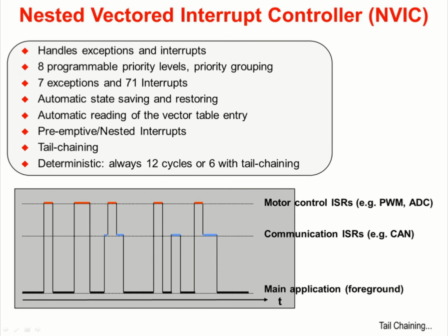One of the first rules that you learn when programming interrupts on a microcontroller is to not nest interrupts. But sometimes you need to nest interrupts. For instance, you need to get a very low latency motor control or device quickly taken care of. You need to get to it quickly, and you have other interrupts that take too long. Those long interrupt service routines will need to be interruptible. On most microcontrollers, you'll have to program this tedious process in software.